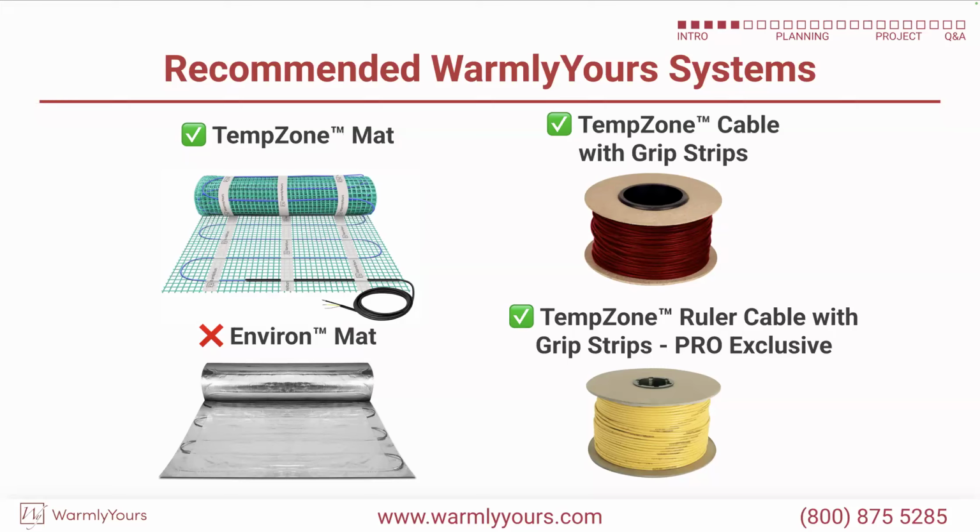You can cut and turn the mesh netting using our pattern on our smart plan that we provide you, so you can maneuver and fit the heat mat to the shape of your space and room. The wires are only 3/8 of an inch, so it's very easy to put your cement right over the top of that and embed it up to a 1/2 inch thick. That's my first choice.